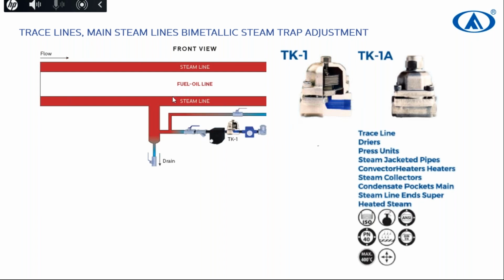Unfortunately, it will affect the discharge capacity. You cannot find much more than float type. But I kindly advise you to use a bimetallic steam trap. Just ask for thermodynamic or bimetallic for less differential pressure. So I answered this, the heat exchanger question. Yes, I answered this.